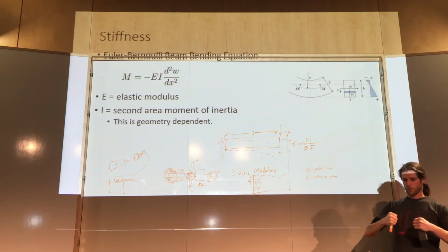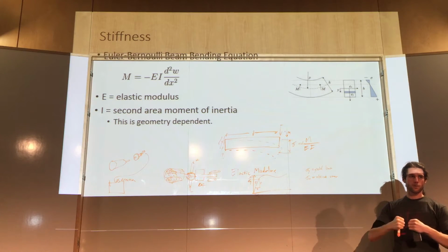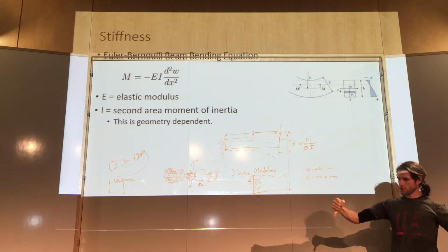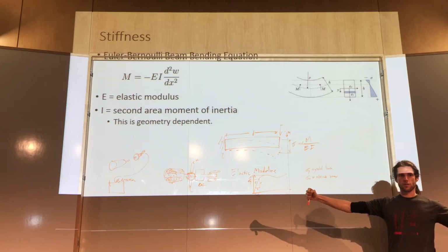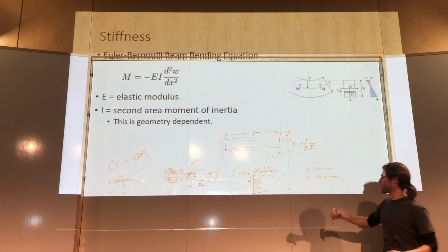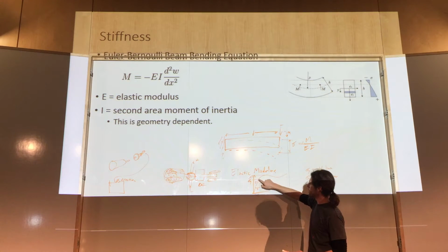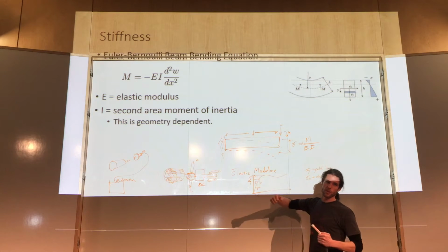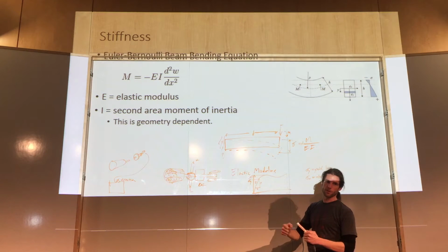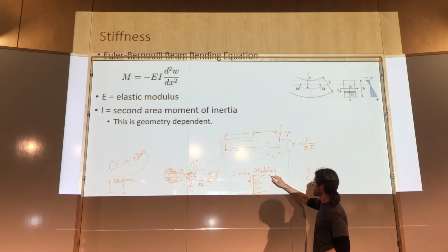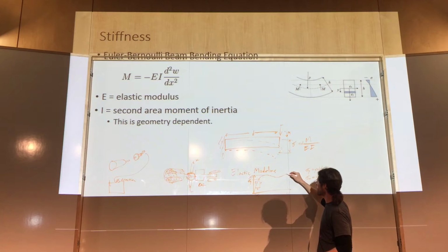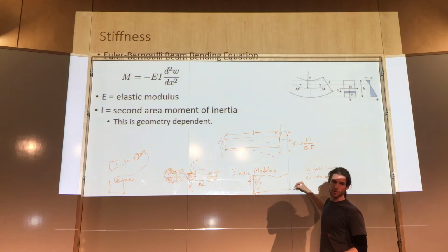You can pull on it a little bit and it returns. But if you pull on it slowly, it stretches and stretches and stretches. It's still holding some force, but you've entered the plastic zone. When you're just pulling a little bit, you're in this linear zone. As soon as it starts stretching out and is not going to return to its shape, you've entered the plastic deformation zone. And then eventually it breaks somewhere out here.